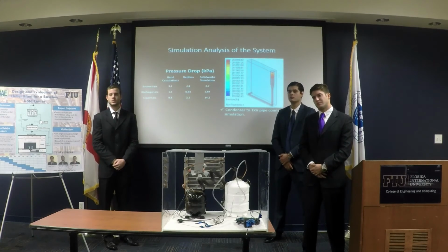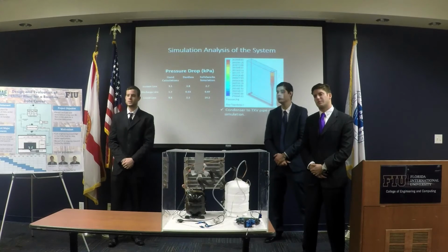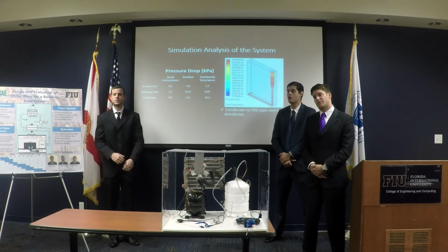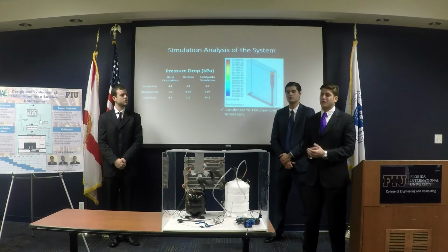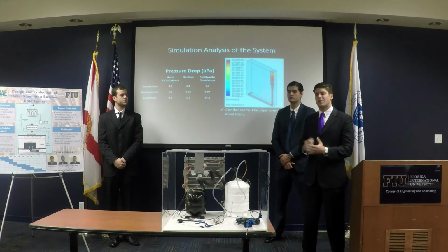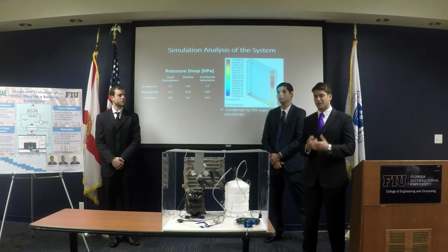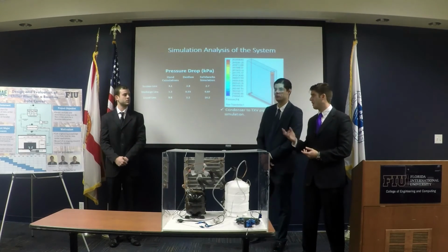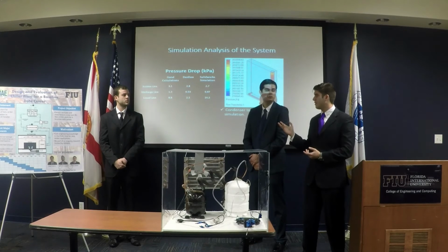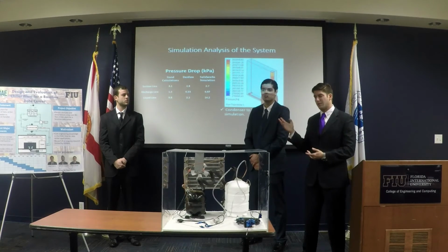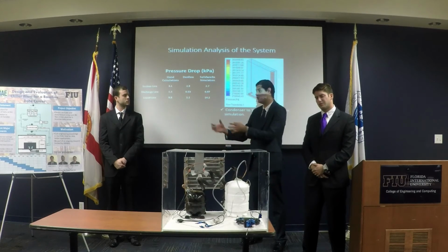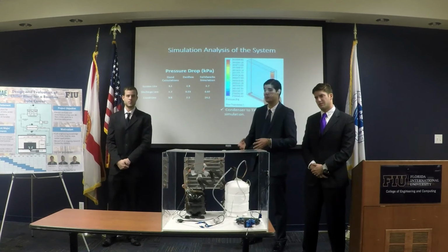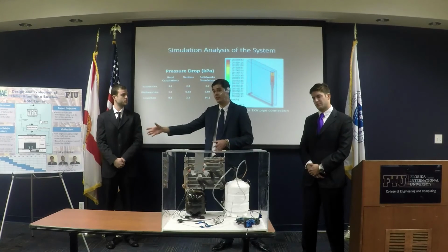Okay, thank you. How did you determine 36 tons? Right in the beginning, you began with something. That was the specification given to us, as well as 120 kilowatts of the research, and when we did the calculation, we got 35 tons. The cooling capacity of the chiller was given to us, and that is coming from the data center cooling needs.